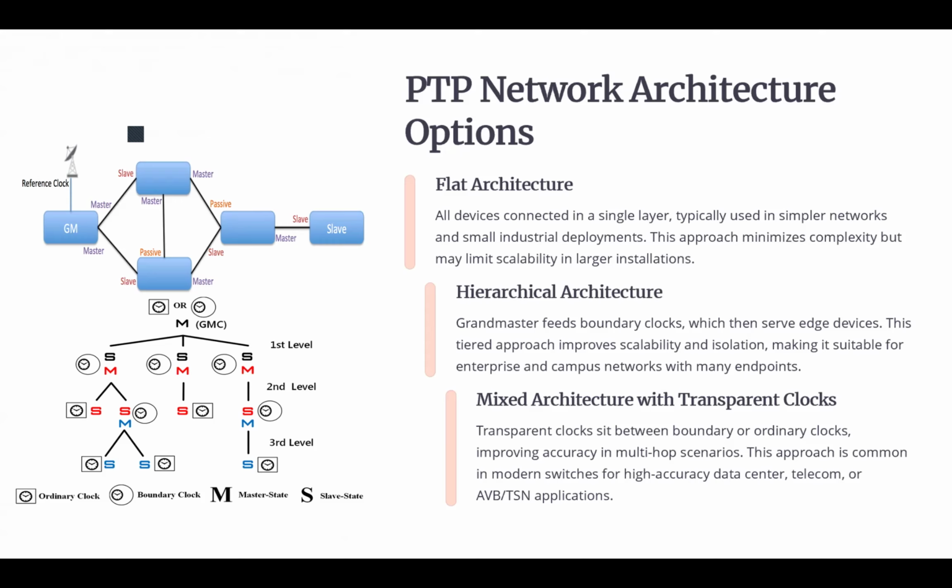So when we have a large or distributed system, that type of architecture would have problems regarding network congestion and timing degradation. The bigger the setup, too many devices receiving the message directly from one grandmaster can cause delays, errors, or synchronization breakdowns.